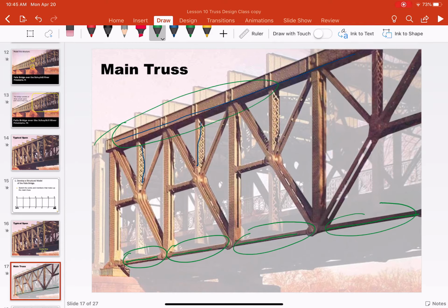And that's the concept: the top chord, or this chord, is in compression. You have to design for both buckling and yielding, and the buckling tends to govern, and that makes the size much bigger than the bottom chord. Make sense, everyone?